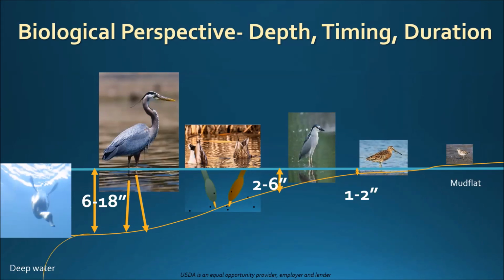Often we will have areas that may be deeper during high water periods of the year, but even those should not exceed 3 to 5 feet. Much deeper, and you're getting into diving duck depths. That's a tongue twister. And many diving duck species are looking for larger bodies of water, not necessarily our wetlands. Think lakes and reservoirs. So although there will be deep areas in wetlands we plan, we're really targeting this 18-inch or shallower and even up to that mud flat depths on site.